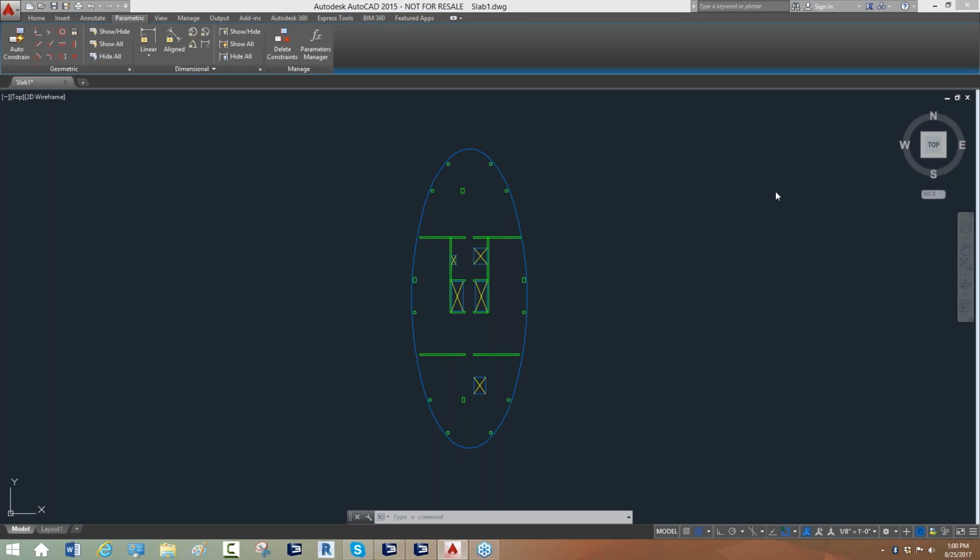So we're going to start at a pretty basic level in terms of building the model, modeling support lines and design strips, modeling tendons, and then evaluating the slab for considerations relative to PT design, for example, pre-compression, balance loading, and allowable tensile and compressive stress.